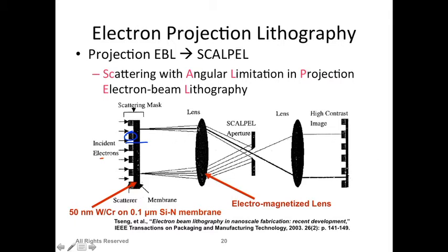So you will see some spreading, but less spreading, or less scattering, as compared to the areas which were opaque. Let's say in this case, this square block, whenever electrons hit that area, you will see more scattering because they are thick, and also you have metals there. So they scatter more of the electron beam. So when they scatter more, again passing through the aperture, you will still get something on the surface, but it would be of low energy.